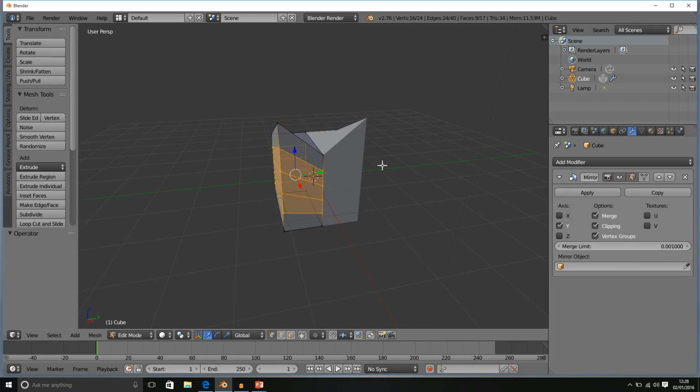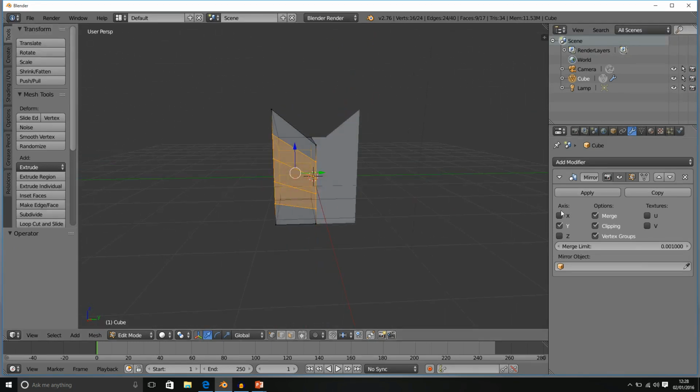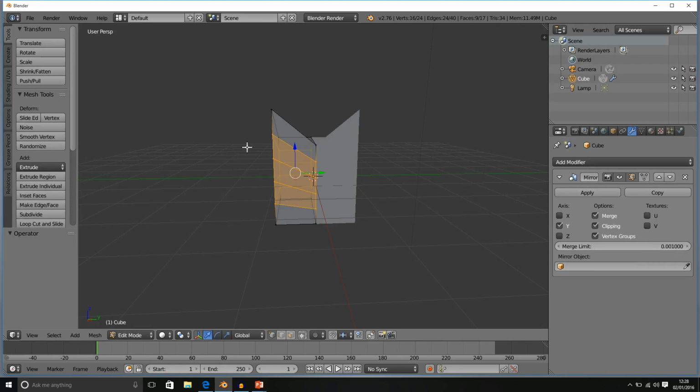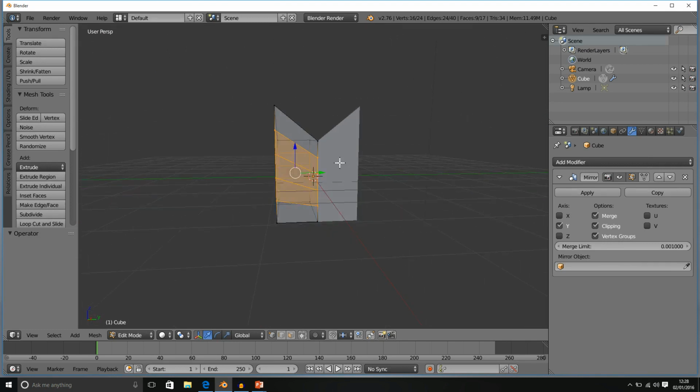So we need to make sure that that is working. So we're going to undo. The reason why it's not working is actually very simple. Even though we have clipping engaged, as we scale smaller, we have it nice and tight, but as it comes out, it seems to almost disconnect from the clip. The reason is that we can't scale out with the clipping always applied. Blender doesn't really allow this very well, because if you're clipped and it's preventing you from scaling, then you can't scale. So scaling takes priority. So just bear that in mind.